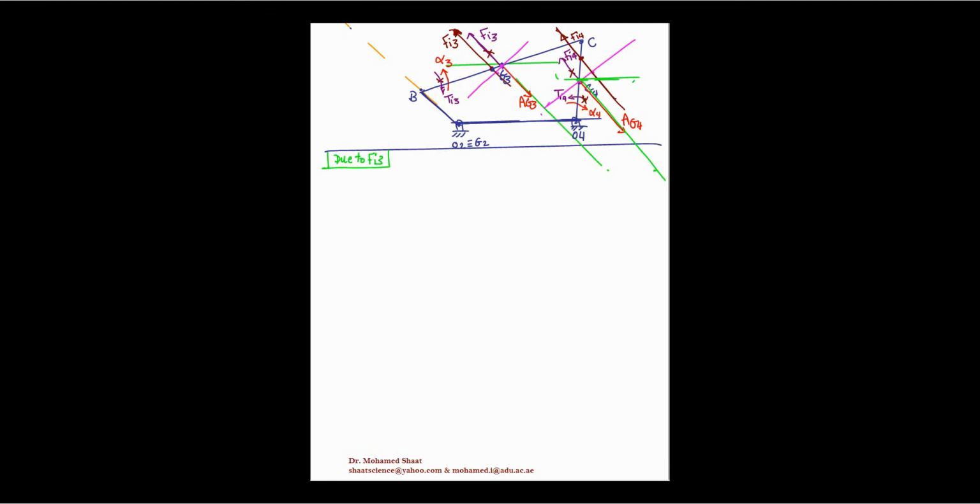So starting with link BC, I'm just going to draw a line, and make sure that this line is completely parallel. And you are going to measure over this line the distance from any point, starting from this point, for example, as point B. Then you are going to go all the way to measure up to point C. This is going to give us link number 3. And mark this, this is point B, and this definitely is going to give us point C.